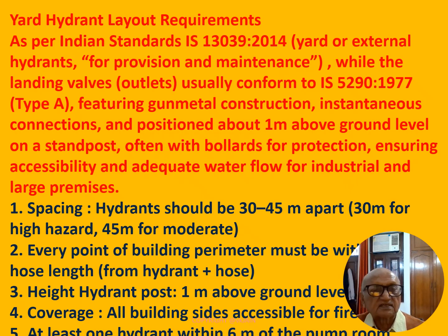As per Indian Standard IS 13039 of 2014, yard or external hydrant provision and maintenance, while the landing valves should conform to Indian Standard 5290 of 1997 type A, featuring gunmetal construction, instantaneous connections, and positioned about 1 meter above ground level on the standpost, often with a bollard for protection.